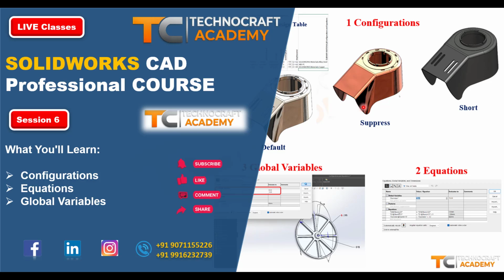So for that we have configurations inside SolidWorks. You can just save the model in a single file with multiple variants in a chart, 100 or 200, whatever it is. You can even generate the Excel table for that, and it is very easy to modify everything and save it whenever you want. Again, you can open it, activate the particular variant and make the modifications. So this is how easy it is. This is about the configurations.